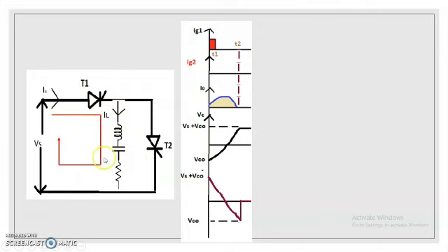Already, the values of R, L and C are selected in such a way that they satisfy the underdamped condition. Underdamped condition is nothing but it will produce an oscillatory waveform. Therefore, the load current will increase, reach the maximum value and then decrease back to 0.